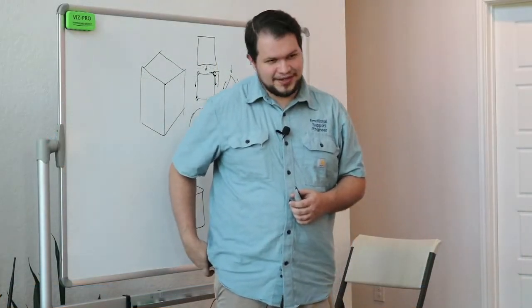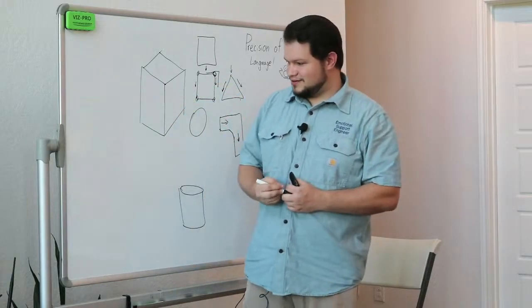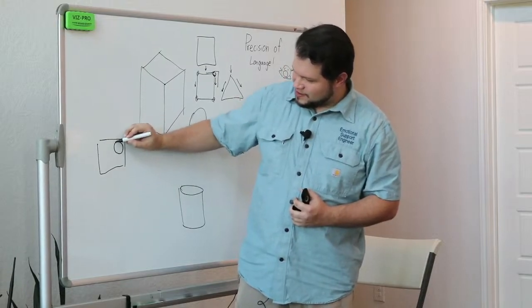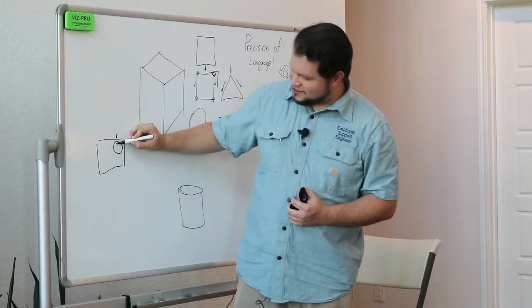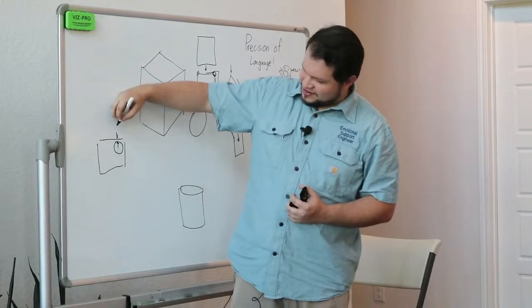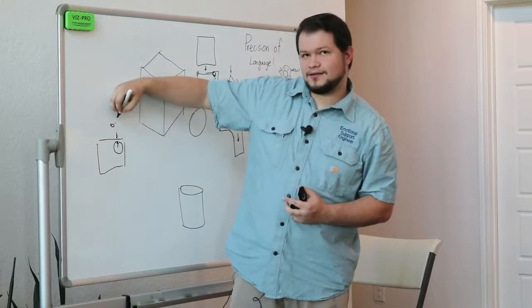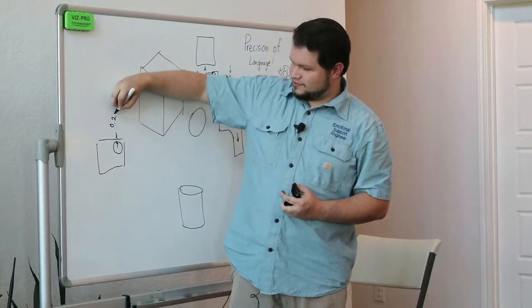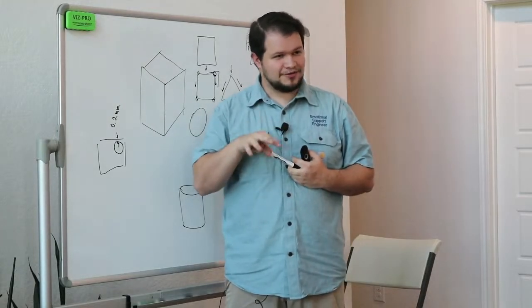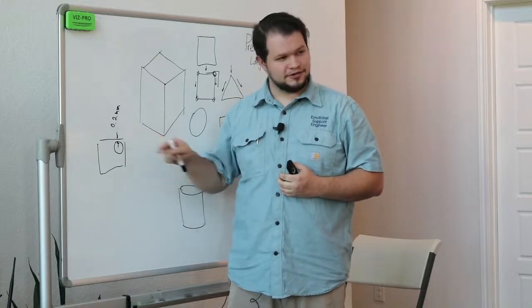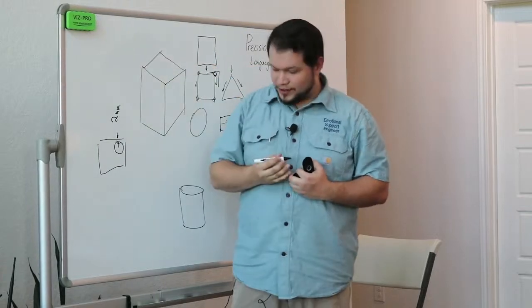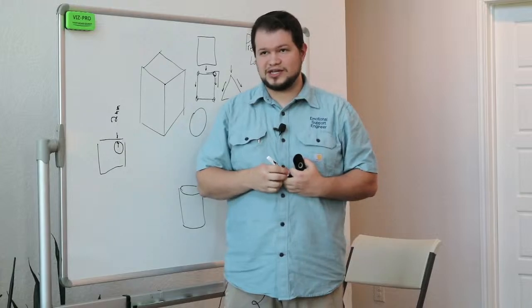Poor material condition is this idea that if I am putting a box together and I want to put a hole here, and I get that hole really close to this edge, let's say 0.2 millimeters, that's really thin. It's not going to take a whole lot for me to break through that wall. That's a poor material condition. So if instead I change this to a full 2 millimeters instead of 0.2 millimeters, it makes it a lot stronger, and it can withstand a lot more force.